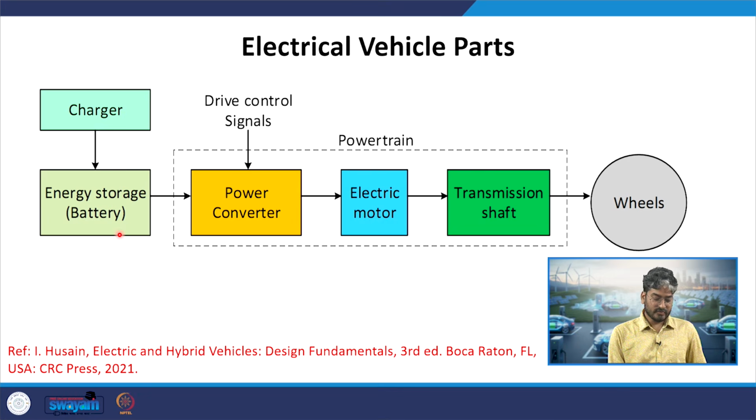First stage: as we have a battery bank, its voltage, although we assume it to be constant for all our analysis, practically changes when the SOC, or the state of charge, of the vehicle changes, and its terminal voltage will change. So it will be producing a variable voltage at this point. This variable voltage cannot be directly fed to a motor which requires variation in its fed voltage such that the speed of the vehicle can change.